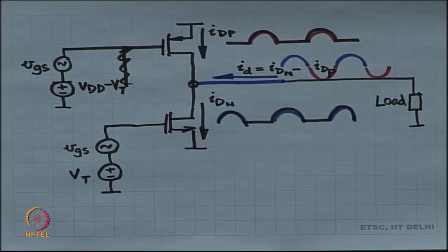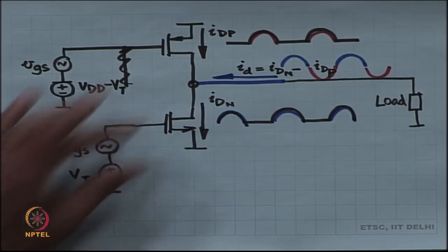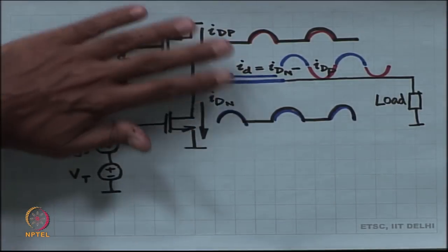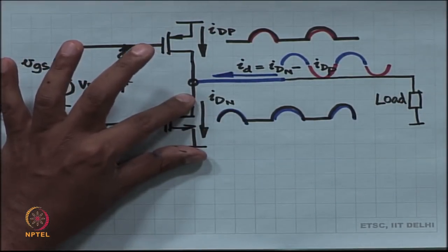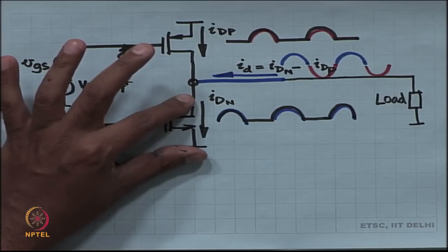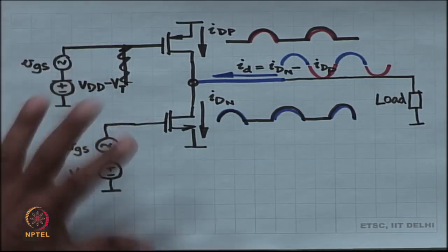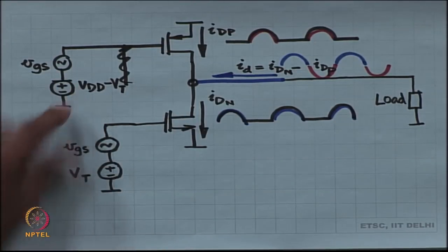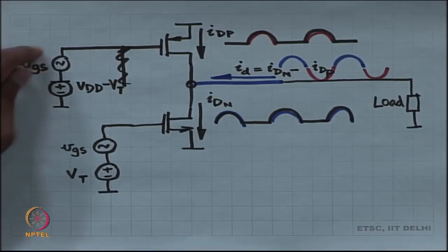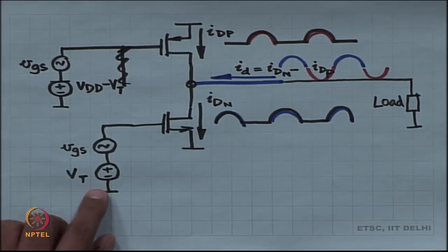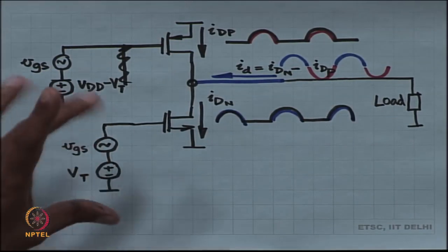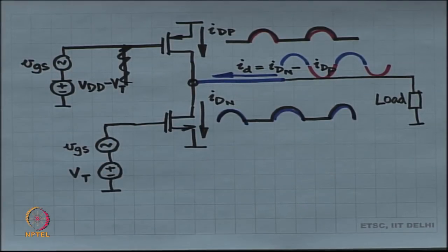The efficiency of this power amplifier is exactly the same as that of the original class B. All that you have done is you have replaced the inductor with the PMOS, right, and for the PMOS you have replaced the inductor with an NMOS. Okay. And then you have to organize these bias voltages. These bias voltages are critical. Okay. You have to organize this to be perfect such that the PMOS is class B. You have to organize this as perfect such that the NMOS is in class B. Once you have organized the bias voltages, everything is going to fall into place.